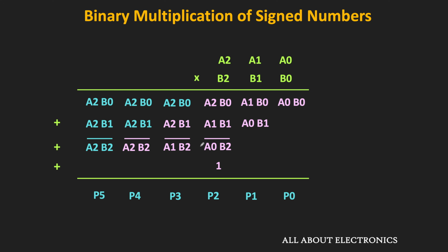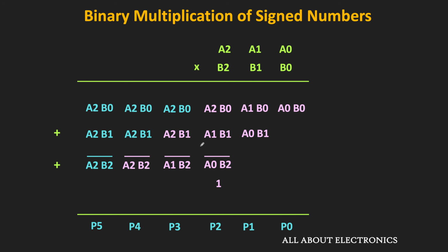So here, once again, the multiplication of the 3-bit signed number is shown. Now in this multiplication, at 3 different locations, the 1 is added and subtracted. So if you see over here, in 3 different columns, the 1 is added and subtracted. So overall, the multiplication will remain the same. But because of this operation, now these additional sign extension bits will vanish. So let us see how.